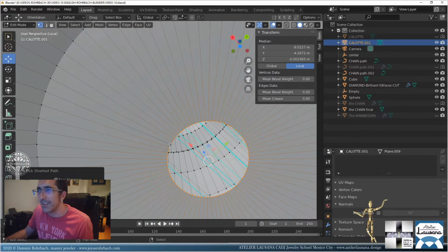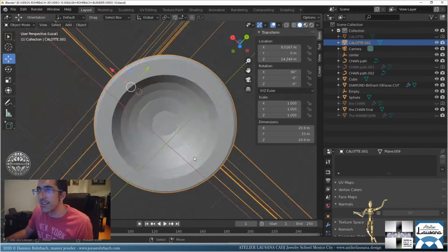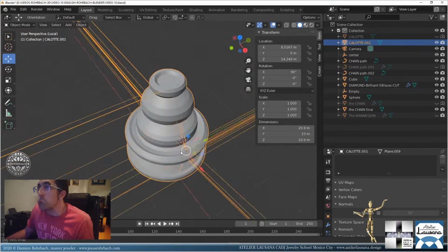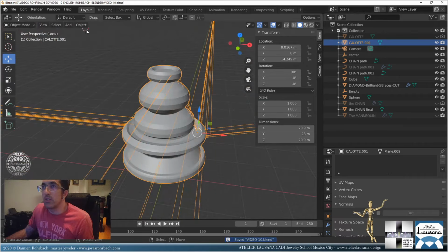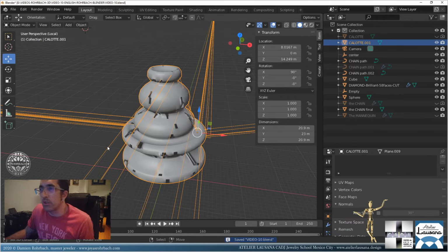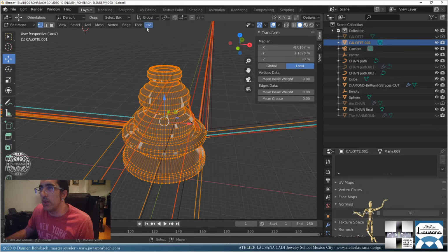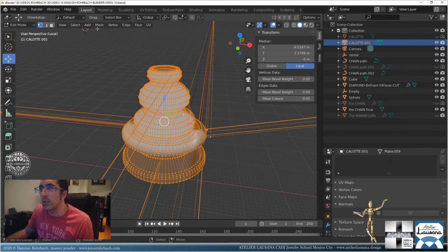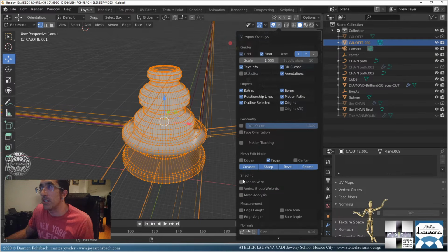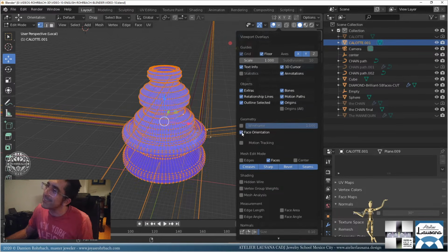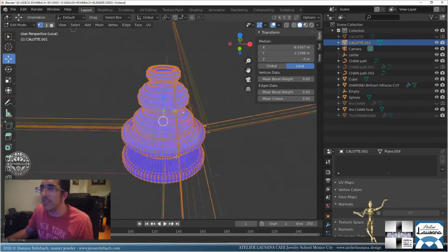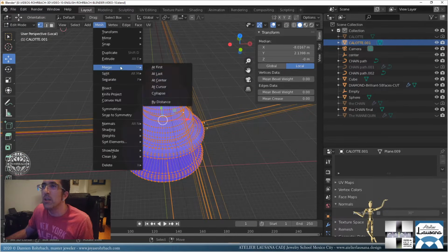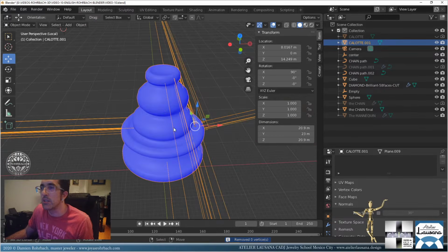Okay, I'm going to F this. We'll see if it bothers the render or something, maybe. Alright, yeah, it is crazy. We have a very slight problem with normals outside. Face orientation. Okay, the face orientation is pretty good. Let's go to merge again by distance.